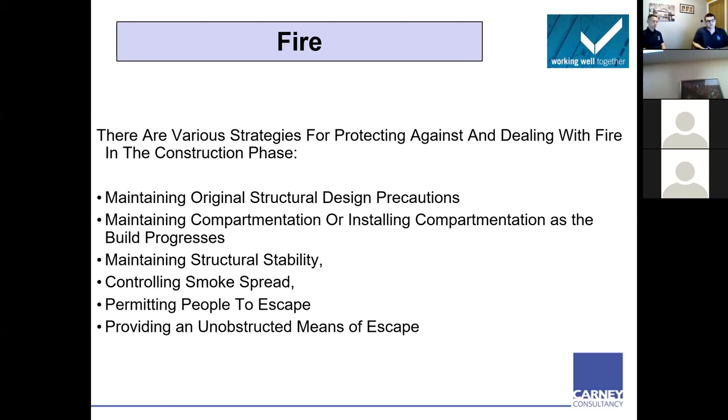If you are doing refurbishment work, you might have to take structural walls or fire lined walls down. Again, what's your plan? What have you done about that? Because potentially, we'll go back to dust. Existing smoke alarms or existing fire alarm systems are bagged to prevent the dust getting in and setting it off and creating false alarms. But if that's left on, there's not going to be any detection.